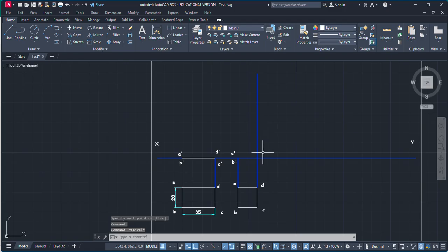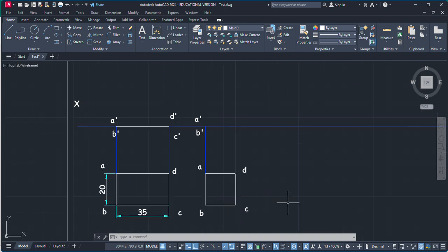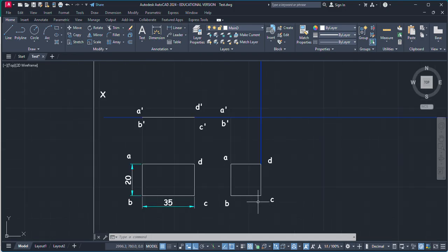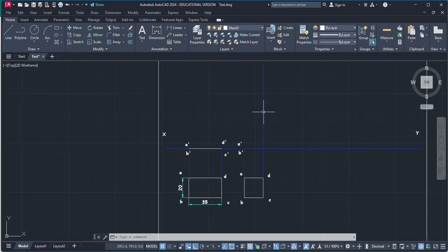We know the second edge will be on this vertical line because, up to now, in the second step we need to copy this thing and incline it to the angle which is given in the question, and from there you need to track the line, with which you will find out the Z. Here we are just reversing the process. We have the top view. Now we need to find the front view.